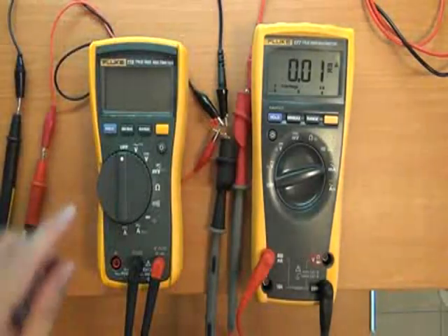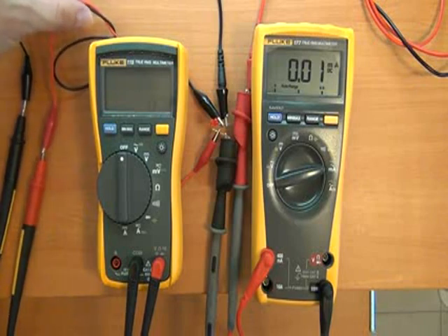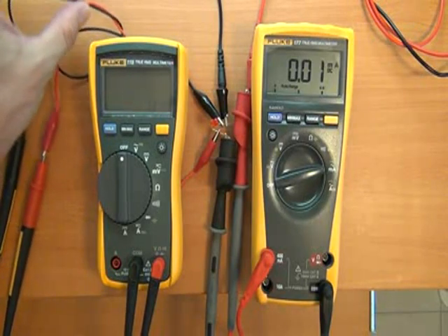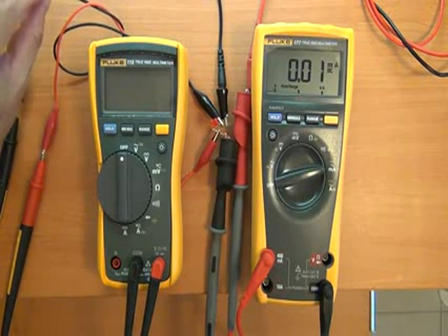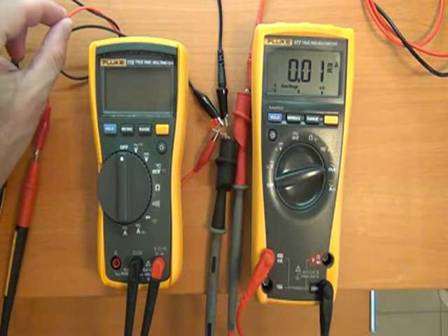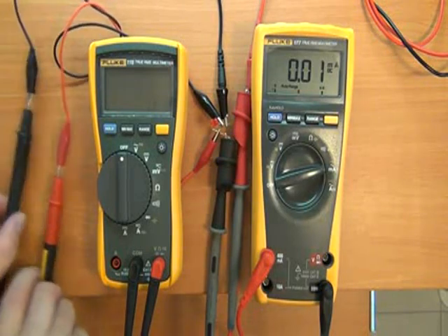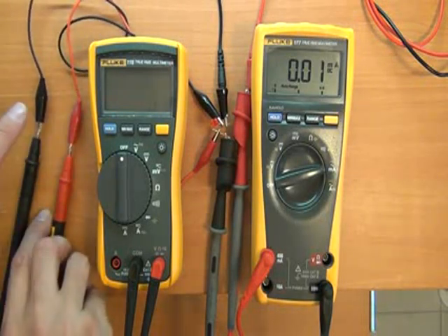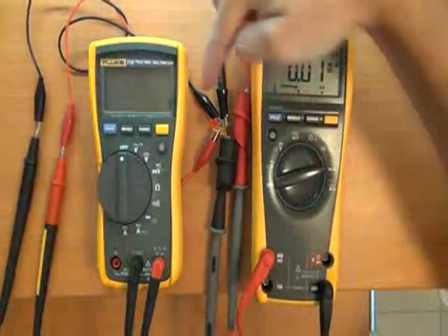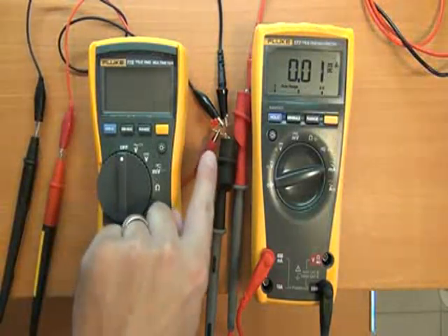Okay, so in this case you'll see I am using these nasty little crocodile clips and these thin wires, but remember, for voltage you can get away with doing that. It's not best practice, but you can do that because you haven't got a lot of current flowing through these. So here they are, positive, negative. Positive lead is on the positive side of the LED over here.